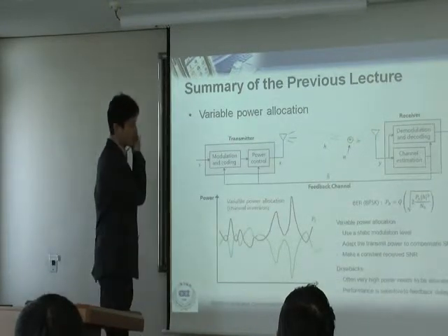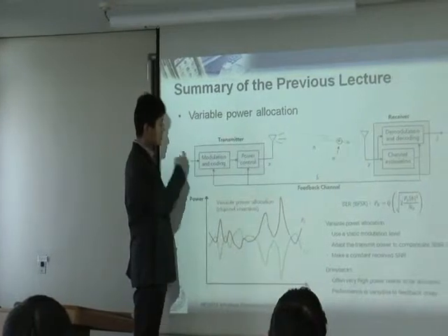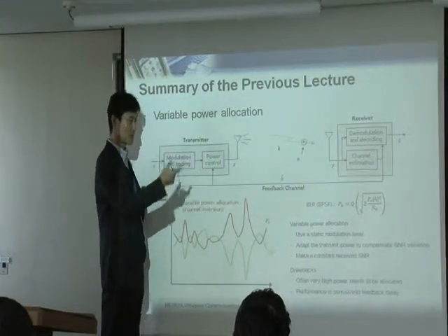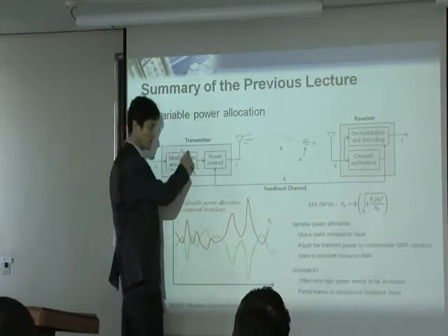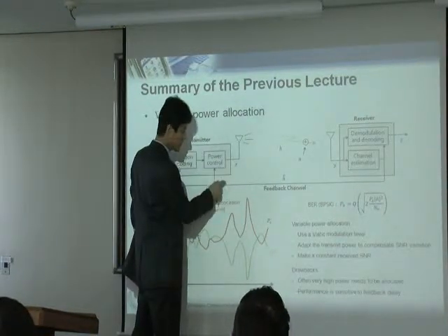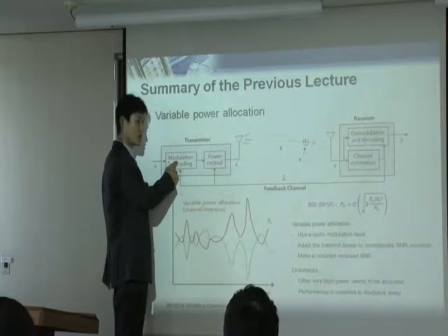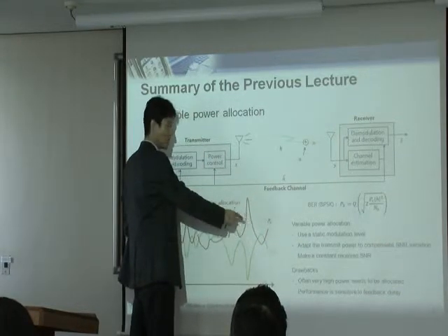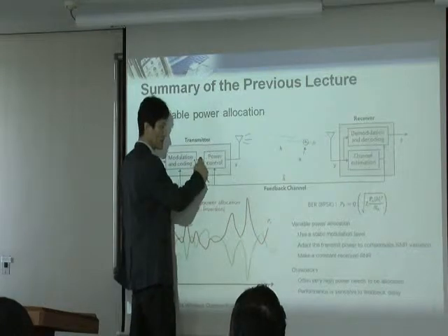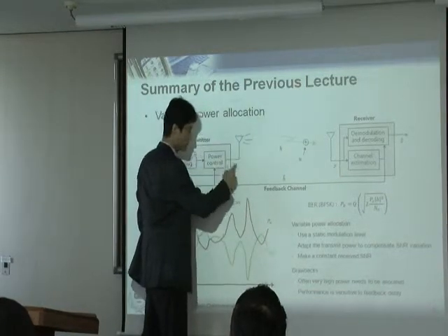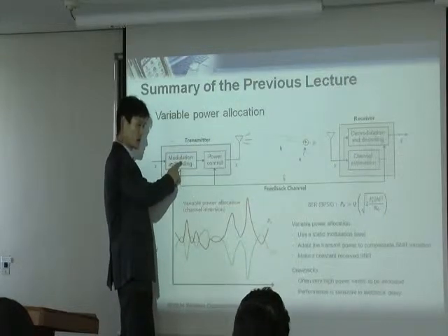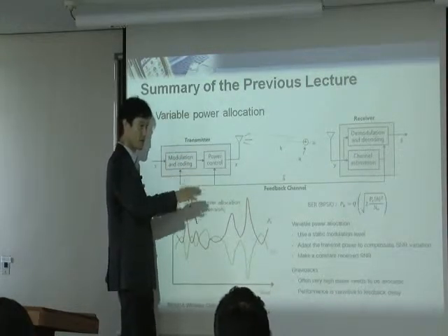The first one here, basically the assumption is that we are not changing the modulation or coding. So from the bit error rate perspective, what you're saying is right. In this case, we are not changing the modulation, so you just follow one curve, just keep going down, if you use a power control like this. Then this is the bit error rate. For example, suppose that you use QPSK, then you use QPSK forever.